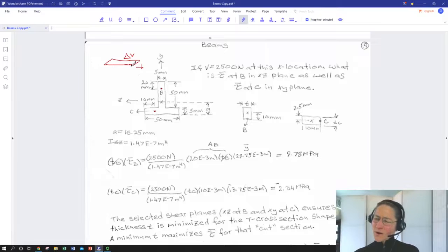So don't we have shear stress at a point now? Well, we kind of have shear stress along a line now, because remember, we didn't shrink t to 0. So what we really have done when we shrunk that delta x to 0, we are now looking at the average shear along the thickness line t. So it's still an average shear.